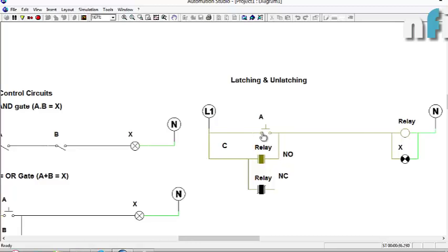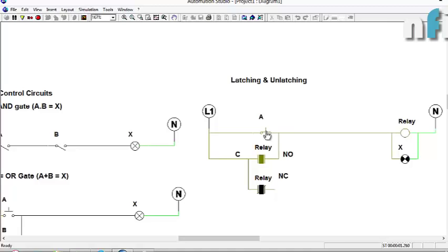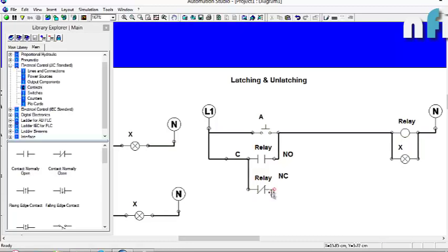Okay, so let me explain again. This is my switch, this is my relay, this is the NO contact. In NO contact, common is not connected to NO when relay is off. That's why it's called normally open. Normally means when relay is off. So when relay is off, common and this NO, there's a strip between that which is not connected. When relay is on, this strip gets connected. When relay is off, this gets disconnected because of spring action. Because of this connection, relay is latched like this. This is the latching. And this NC contact is generally used to indicate when relay is off.